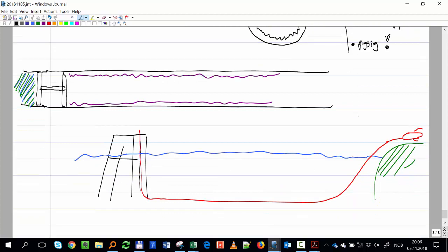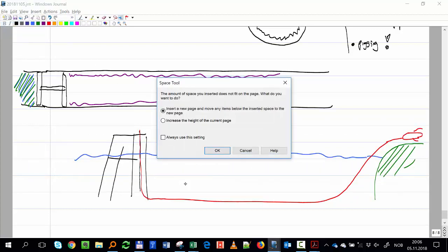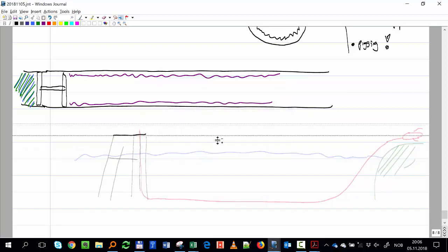So this is called pigging, and you sometimes use it for subsea systems and flow lines. I think now they are thinking about installing an oil pipeline between Tanzania and Uganda, and this is one of the issues: the wax deposition on the walls. So if you know you're going to have accumulation, you have to wait until you have some layer and then you pig. If you wait too much, then remember the pig at some point, sorry for the detour, but I think pigging is important.